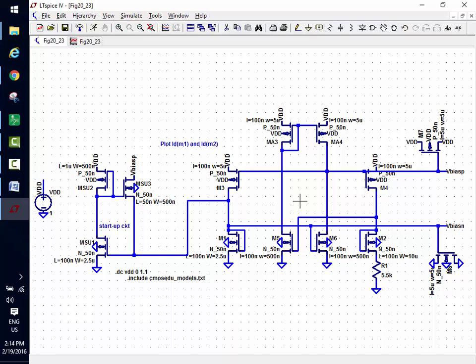What does that do to the gain of this amplifier? If I decrease the current that flows in the amplifier, what do you think happens to the gain? Remember, we covered this. Short question. If I decrease the current, what happens to the gain? gm times r_out. Remember that plot? Lower current, more gain. No, more gain.